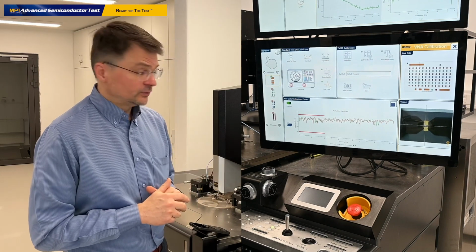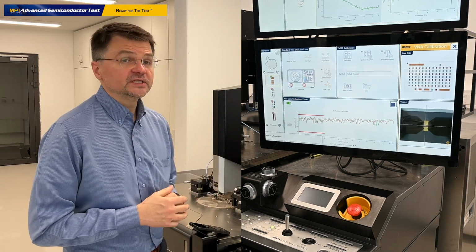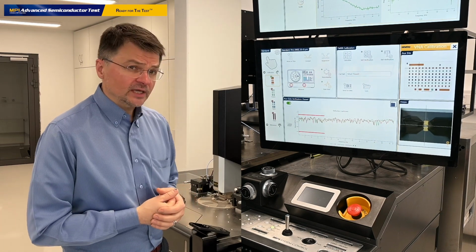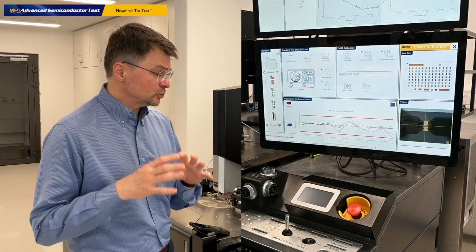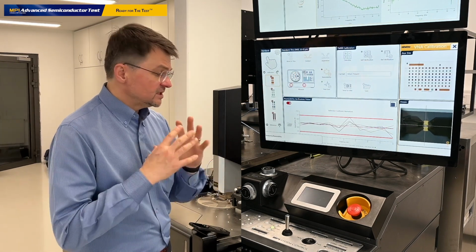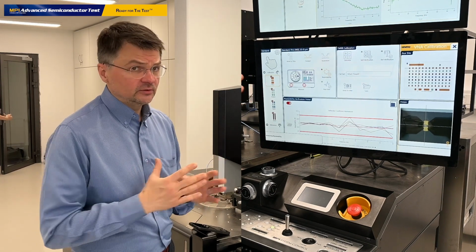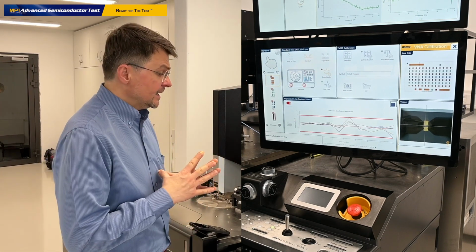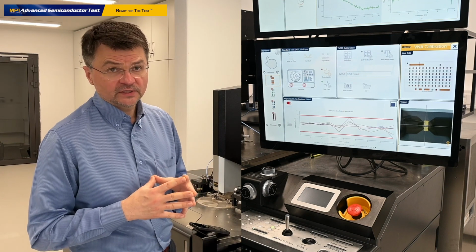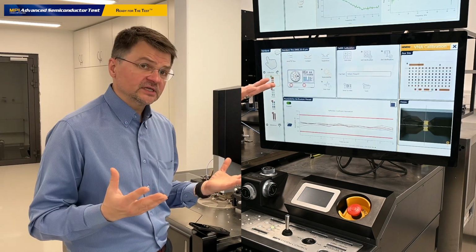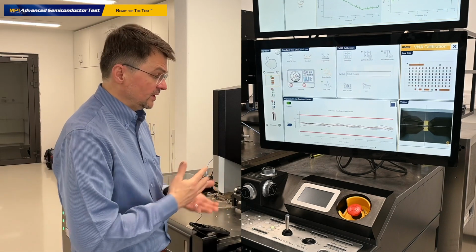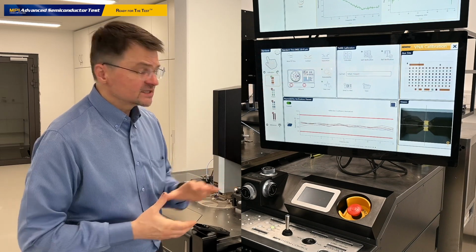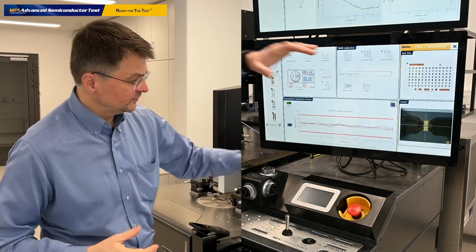So we move to the through calibration standard, and let us trigger and measure the data. Before acquiring raw data of the calibration standard, Calibria also checks for the data repeatability. And we use a special sweep for the data repeatability, which has a different number of frequency points. Usually you need just a few frequency points, like 10 or so, just to understand if the data are repeatable or not. And it can be set for different frequency lists. Because if your data are not repeatable, they are equally unrepeatable on the whole frequency list or just a shortened frequency list. And this is exactly what we've just evaluated on this particular test.